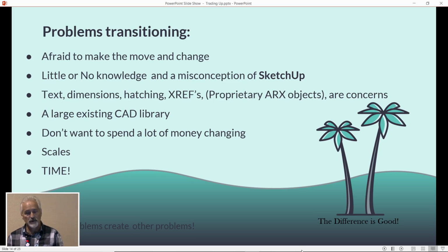If it does translate over, and if you can get it over, and there's a way to get it over, and I'll explain that, I can explode the text during the process I use to work on a CAD file. Then I can get the text to come over, but it is not text. It's lines. SketchUp has problems with hatching. Not all of them. Some do come over.